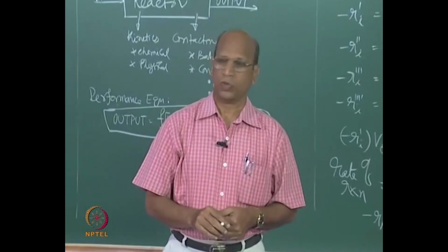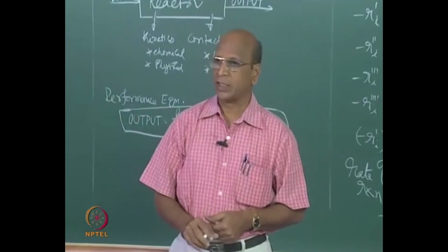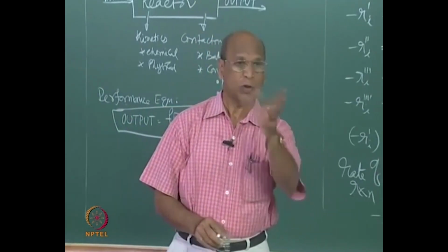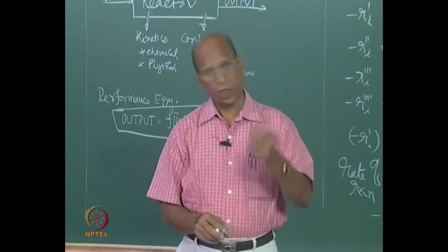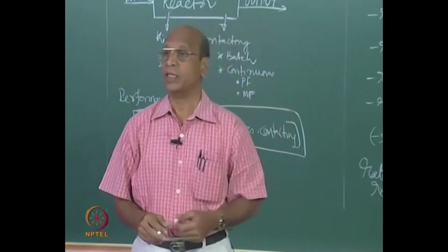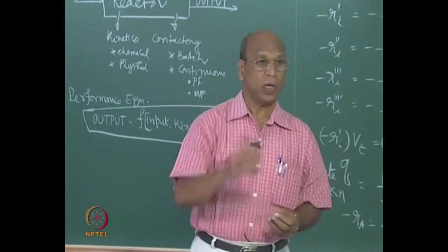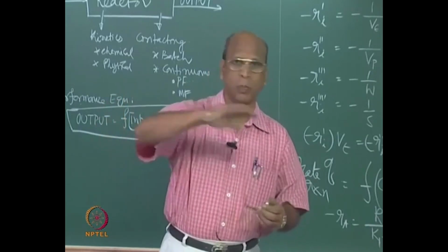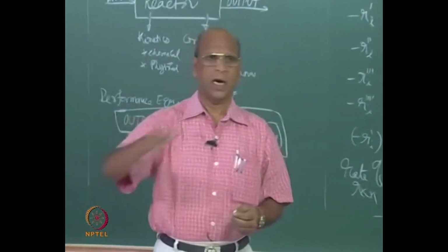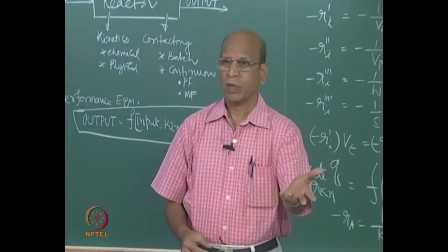But the general thumb rule is, for low production rates, flexibility in production rates and very slow reactions, a batch reactor is used, and a continuous reactor is used for very high production rates and also good quality. And which one will be costly? Initial cost? Continuous, definitely, because it needs more instrumentation and all that. But still we go for it, because you have done your project by taking depreciation cost and also break even into account. The break even should be as quick as possible.